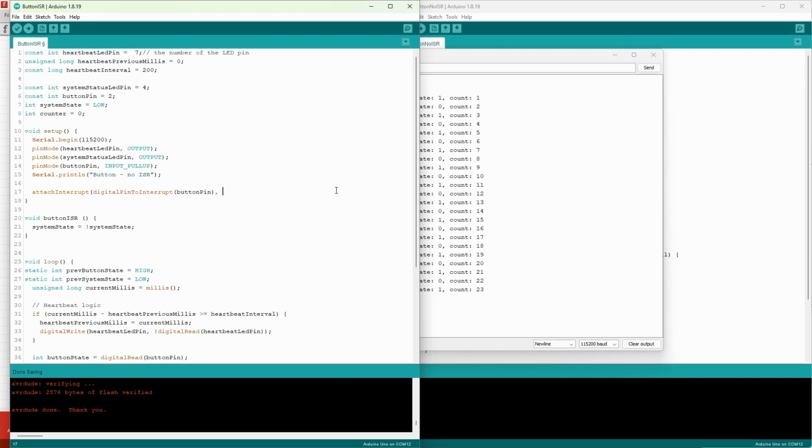It should also be borne in mind that not all pins support interrupts, and the characteristics of some of them are slightly different, so you definitely need to refer to the documentation. This gets back to what I said earlier: it's a little bit technical, and you do need to understand what's going on when you're setting these things up.